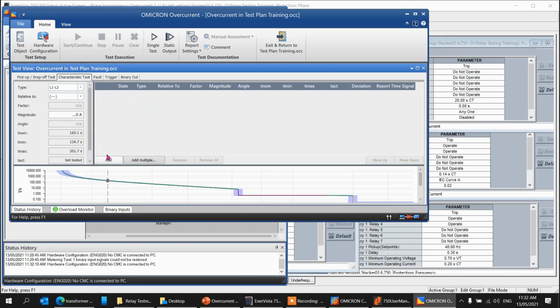If you add this thing here, relative to, this is the one that we created earlier. Remember? Phase overcurrents, stage 1 and stage 2. So at the moment we have to pick this. Normally we do line 1, line 2 for the reason that we have discussed, to avoid tripping the earth fault. So I will do probably basic on that one.